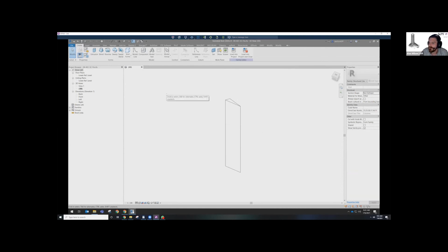The way we ended up creating the fins themselves, we're using a structural column. Structural columns are great because, one, they're super easy to use. Two, they're profile based, so you can just sketch a profile and load it in. And three, they can slant. The fins, while they're only leaning in one direction, they're not twisting. There's none of that. Structural columns are a great solution for this. It allows you to quickly run it over an entire facade instead of getting stuck building it within the adaptive panels themselves.